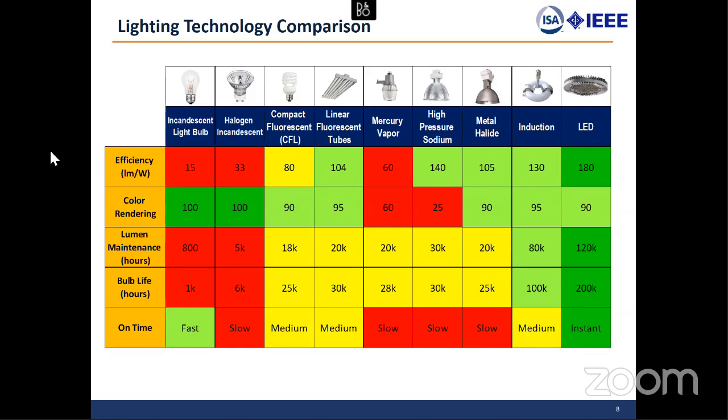And then you can get reports showing you what lights are on. If you have occupancy sensors, you add a section, and it'll show you if your lights are working properly. Are your schedules running? Are people in areas at night they probably shouldn't be, or maybe you've got to light them differently or change your schedule? So there are a lot of different things you can do just from the reporting side.